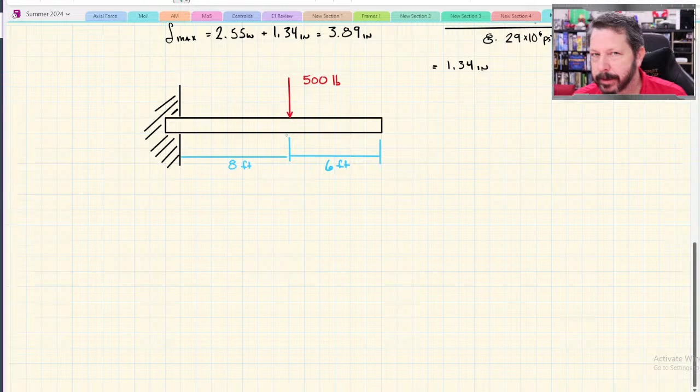The point load's not all the way at the end of the beam. So how we treat this is we did a similar-ish thing yesterday, but not quite the same. This little section of the beam is actually not bending, unless it's bending under its own weight, but we are ignoring self-weight for now. So what this beam would do would look something like this.